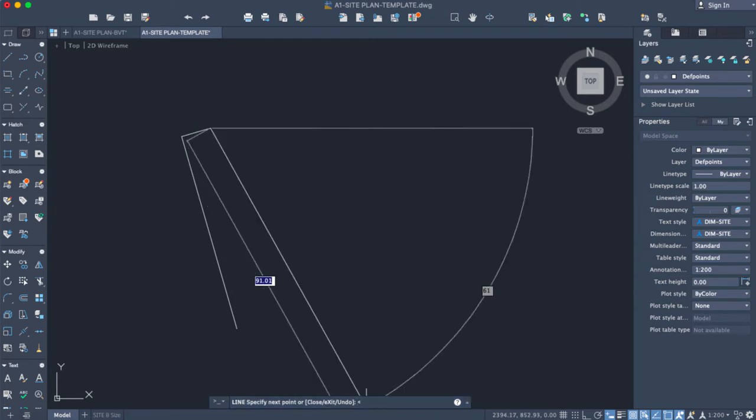Again, I'm repeating: make sure you're putting the angle. Then it says north, so make sure you're putting N for north, 15 D for degrees, 57 minutes. For minutes and seconds, I told you guys to use the same keys that you use for feet and inches. For minutes, it's the feet sign, and for seconds, it's the inch sign that you used to use.